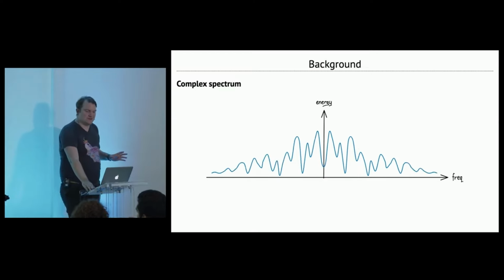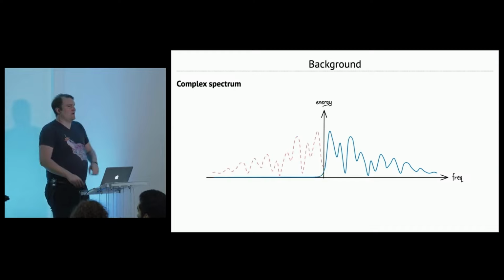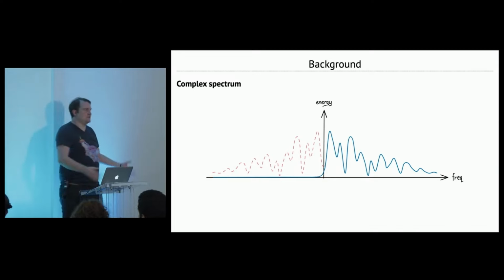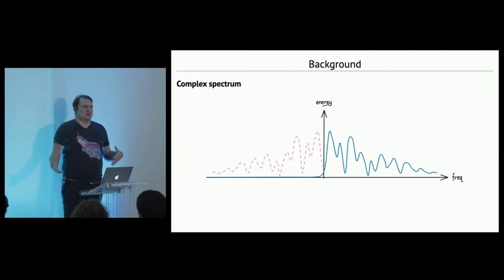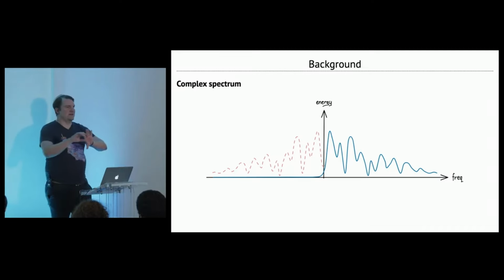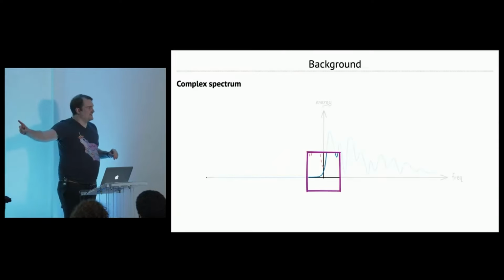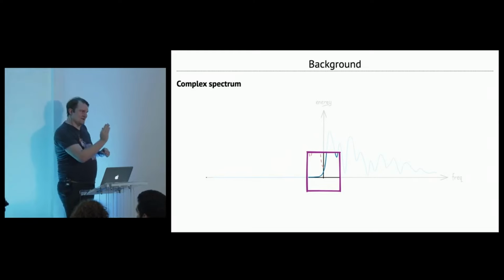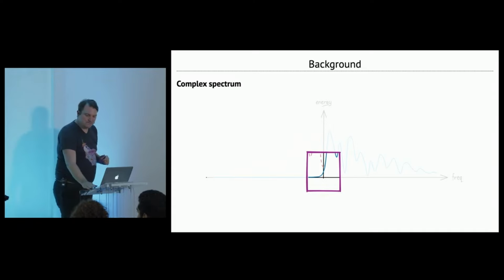So what you really want to do, this is the Hilbert filter, is take your complex spectrum and have a version where all the negative frequencies are gone. Because then you can shift this around, you can do whatever you like with it, and then you won't have that mirrored copy screwing things up when you convert back to real and the symmetry reasserts itself. So a particular interest in this talk is what exactly happens around 0 hertz, the DC component.